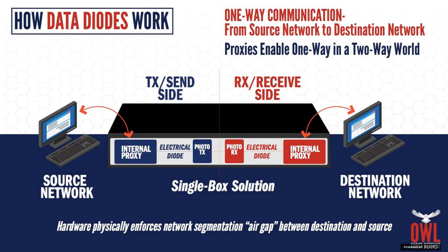So let's say you had some malware that got introduced inside the facility. Somebody walked in with a thumb drive, innocently or not, and needed to put some software on the inside. Unintentionally, some malware gets released inside the plant. Now, a lot of that stuff will phone home and ask, what do you want me to do? Across the diode, because there's no routing information, there's no routing across the platform itself, there's no way for that device to ever phone home.